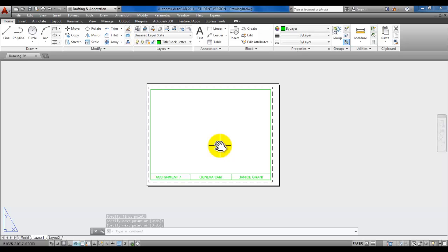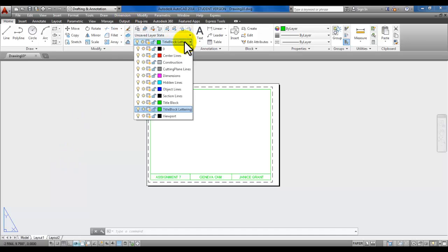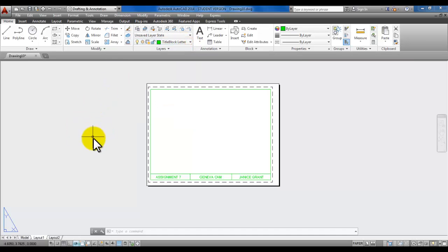Later on, we're going to create a hole in this paper and be able to see the objects that we're creating in this model space. But what we're doing is we're creating these settings. We haven't saved this file yet because we're establishing our standards. What do we have? We have layers, we have some settings, and we have this layout space that's created. Now we're going to save it as a template.